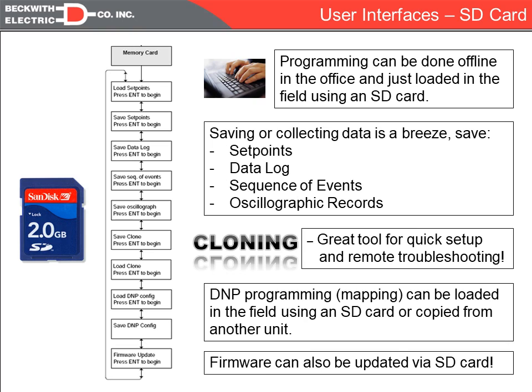With the H, we've also added an SD card. So we have a card slot on the front of the control. It uses a standard SD card. And if the card is plugged into the control, when you hit the communications button from the main menu, if it reads the card, i.e. it's properly formatted, then it'll come up with the memory card menu. Hitting the down arrow will allow you to select any of these quantities.